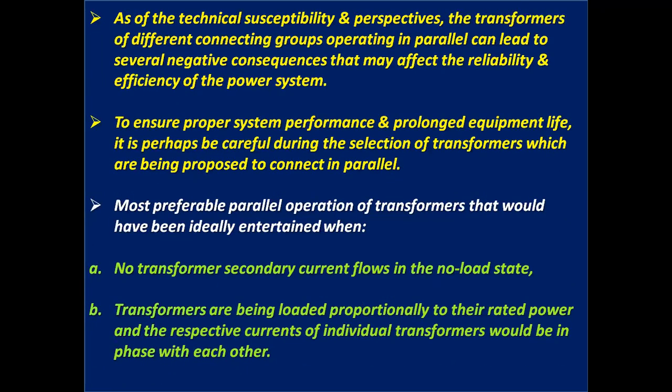From the technical perspective, transformers of different connecting groups operating in parallel can lead to several negative consequences that may affect the reliability and efficiency of the power system. To ensure proper system performance and prolonged equipment life, one must be careful during the selection of transformers which are proposed to be connected in parallel.